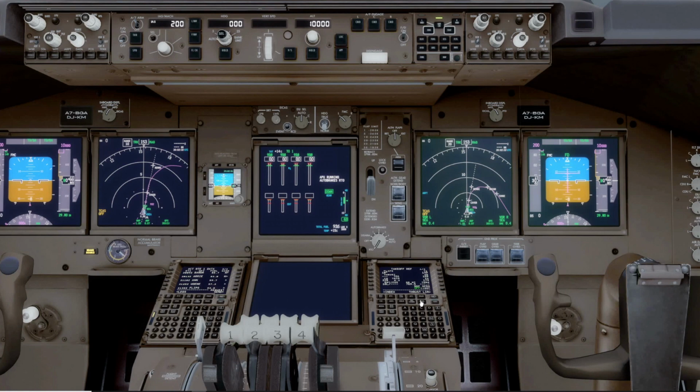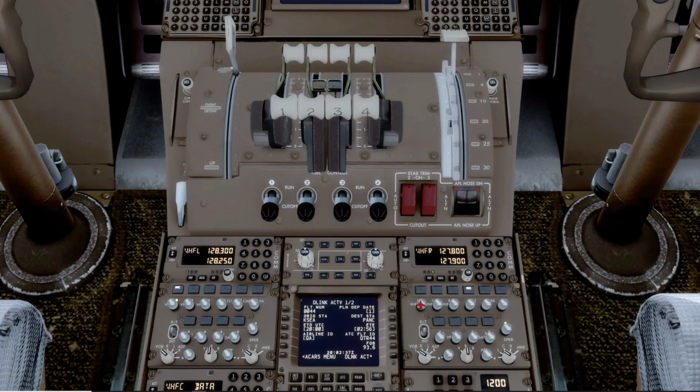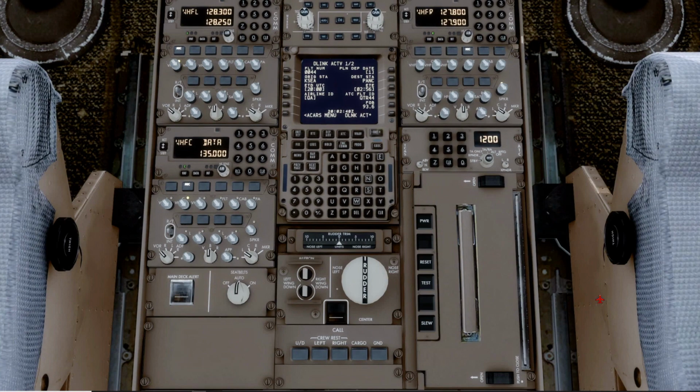And then from there I can come down to the audio panel, the lower panel. And I'll check the captain's radio tuning panel, that it's, again, whatever frequencies I want in here right now I could put. Normally the left radio tuning panel will be used for ground and tower and departure and center and things like that, and the right radio tuning panel will be used for ATIS and clearances and company and things like that, and then the center will be used primarily for the data link system, which it's on right now.